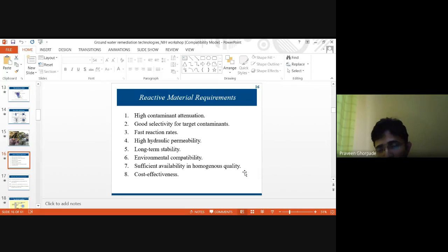Now when we look into all these types of problems, and there is a material naturally available in a system, there is something called the river bank filtration technique, RBF. This is ongoing work in the Tungabhadra river basin, where the natural water from the river is flowing, and on the banks of the river they drill borewells or wells. When the water flows into those wells, naturally that water gets filtered through the soil strata which is present, and that soil strata has the capacity to treat some of those pollutants.